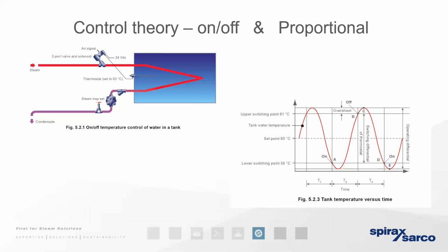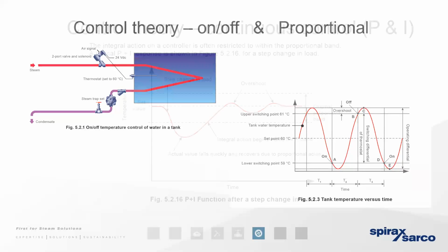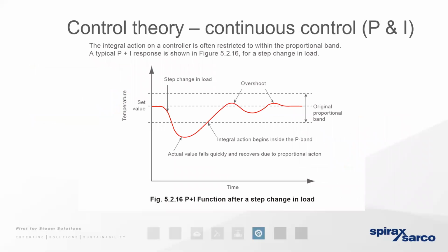And we can improve upon that and move away from proportional control towards what we refer to as proportional and integral. Proportional control is only available in self-acting valve types. If we want to improve upon proportional control, we need to move towards an actuated control valve. So if we add in integral, then you can see that it's able to predict the required step changes and start to smooth out that proportional band.